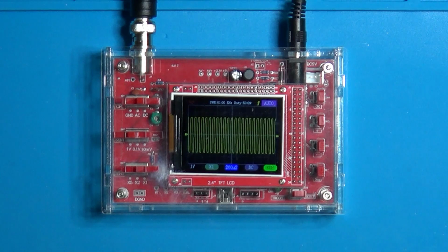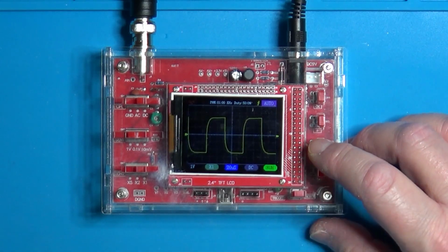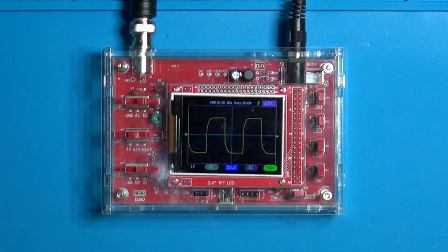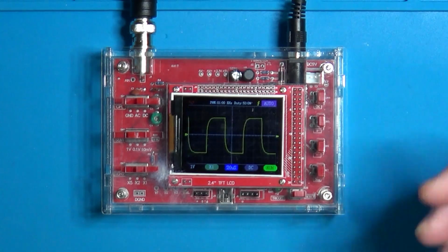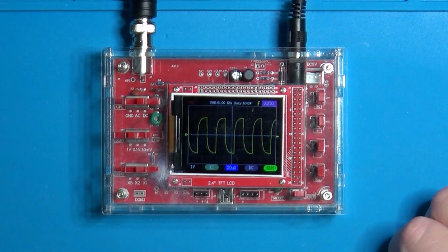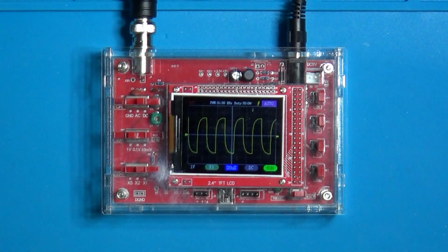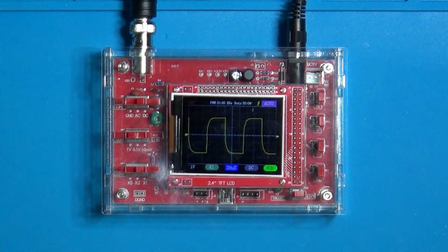Okay, now we can see that the oscilloscope is losing some of the high-frequency harmonics. But I guess it is still fine from the perspective of using the oscilloscope for the synth, since we really will not use such high frequencies when making sounds. Let's go to 20 kHz just for the sake of it. Yeah, now the shape is totally distorted, so the oscilloscope is no good at such frequencies, when displaying waves different than sine waves. So back to 10 kHz.